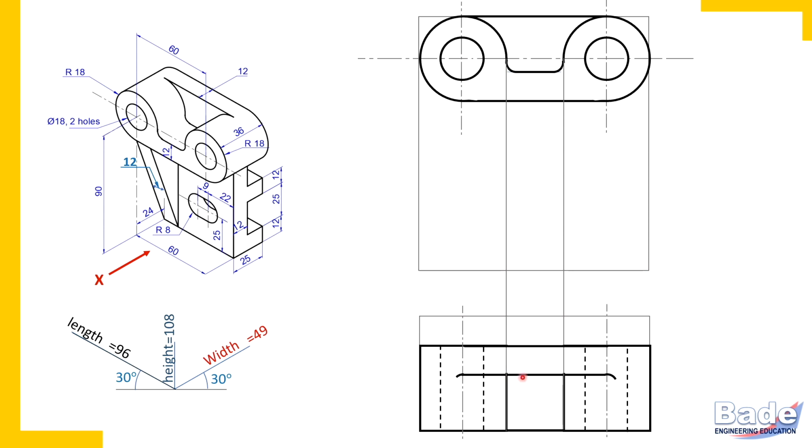Remember this, two visible edges intersecting suggests some correction. And remember, on the boundary generator of a cylinder, if a joint appears, then the boundary of the cylinder inside the joint is to be erased. Now this horizontal plate in the top view, you will have to complete by drawing a dark line here. So this surface, what you are watching here, horizontal surface, you can see here. So this is how the upper portion is complete.